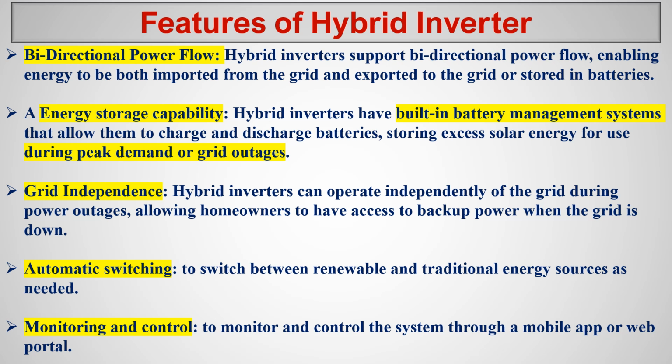So whatever options you want, to remove the grid, or to cut off the battery, I mean you don't want to take the power from the battery, any option is possible by switching. So this switching is smartly programmed in this hybrid inverter. We can modify the program as well, as you are asking, like can I charge 50 percentage and can I export to the grid another 50 percentage during the daytime? Yes, that is possible by using hybrid inverters.